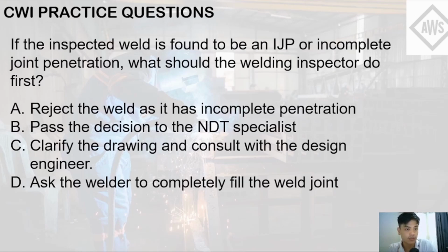Basically, here is letter A. It states that you need to reject the weld as it has incomplete penetration. So basically, some welding procedures or specifications or drawings may not accept incomplete penetration, so that can be an answer. Letter B, pass the decision to the NDT specialist.